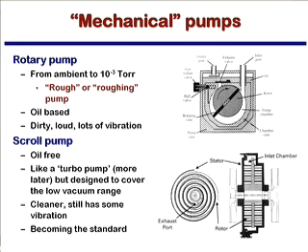And the roughing pump, its major goal is two things. It is used to initiate the vacuum. If you put your microscope in, right, or you've had a problem over the weekend or whatever, where you're not at vacuum, the first thing that goes on is your roughing pump, and it removes most of the gas, takes you from 760 torr down to 10 to the minus 3 torr, and just gets things going.